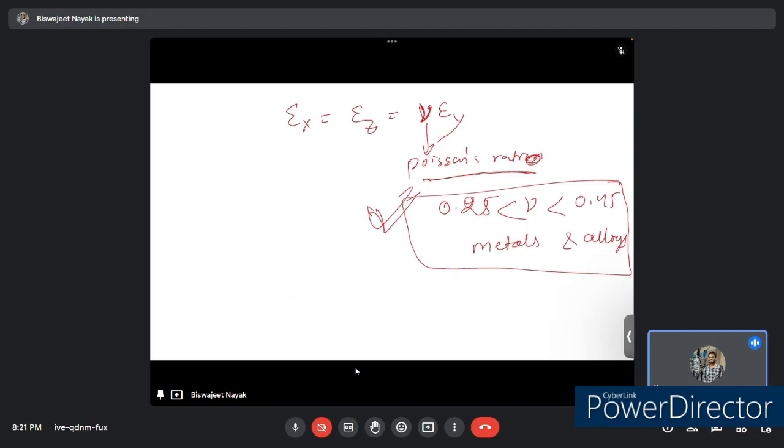To measure Ey here by X-ray would require diffraction from planes perpendicular to the axis of the bar, which is impossible. The diffraction planes parallel to the axis of the bar are used by making a back reflection X-ray measurement.